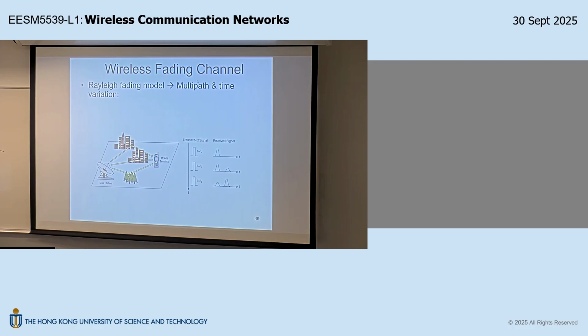It's not just noise, you also have fading. So let me explain the so-called fading. We'll talk about several things. First of all, we have to understand, as we said, right? The first thing we need to do is not to design the transmitter or receiver. The first thing we need to do is to understand the channel. So now we're considering cellular communication, so let's spend some time to understand the mobile cellular channel.